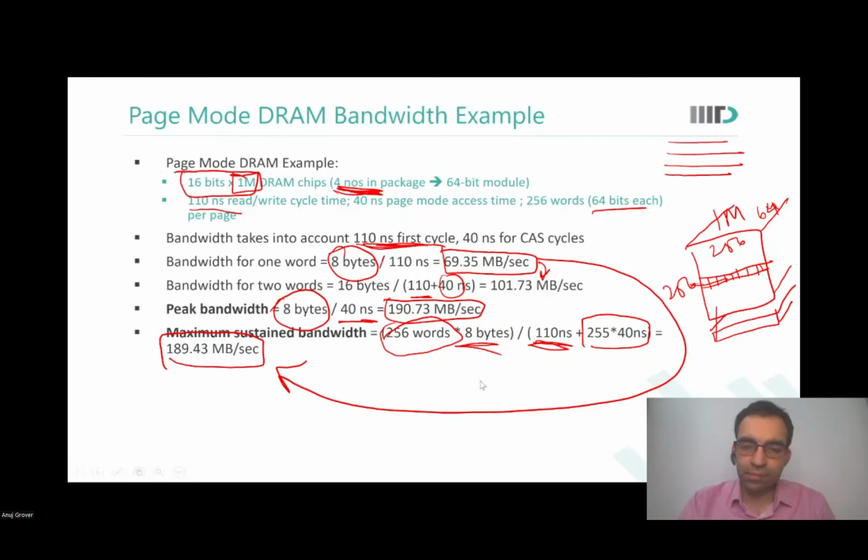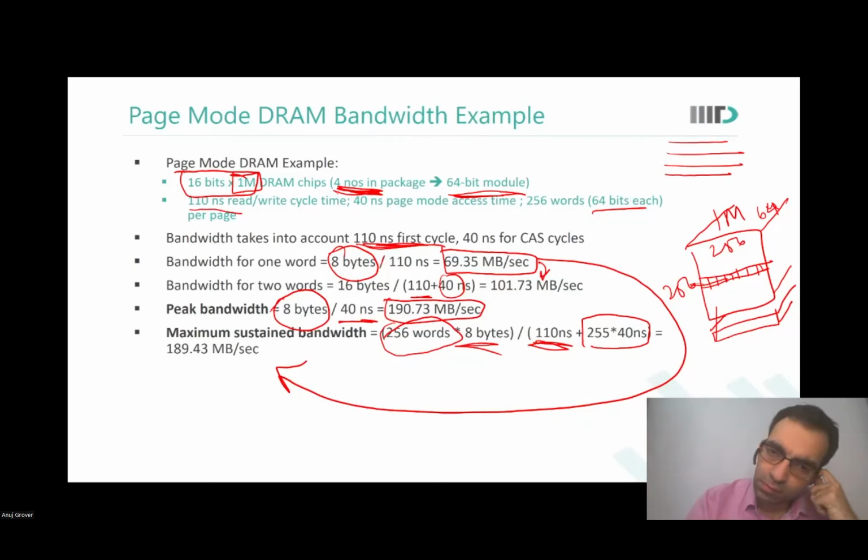So this bandwidth is indicating the output of DRAM. Anyway, the bandwidth which is coming from DRAM to the processor will be 16 bits only in each cycle, because my data bus is 16 bits, right? See, I said that I wanted a 64-bit module, so I could have a 64-bit wide data bus, no? Why would it be 16 bits? Each die will have a data bus, but the package has 4 dies in it, so there are 64 pins that the package has.